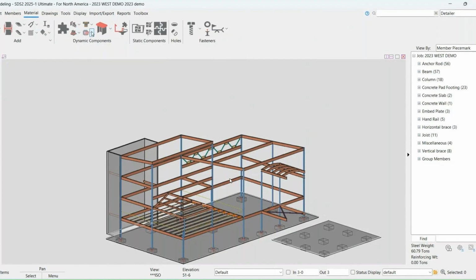Okay, you can add any slab thicknesses. Concrete openings you can add. Then you can add a cap plate or shim plates or any shear keys at the bottom of the column. Then this is for adding post stops. This is for adding an individual hole, or a bolt, stud or welds to a steel.